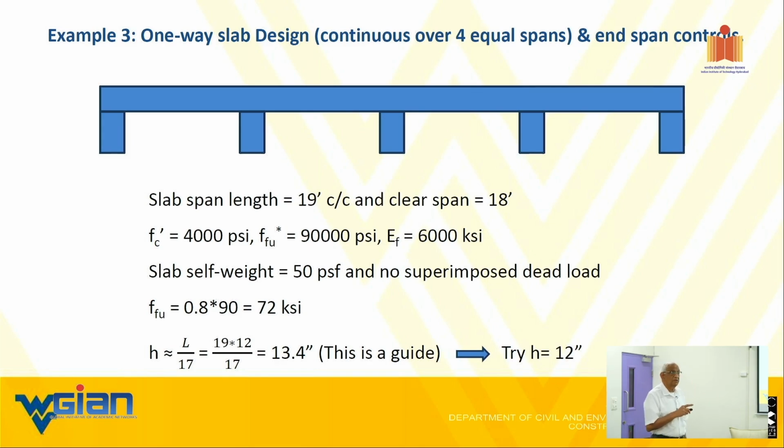So keep it in mind, your average is not what it is. So my message is, I have 110 KSI FRP, while in fact, I am using 72 KSI as my design value. So right away, you almost have a 50% reduction.